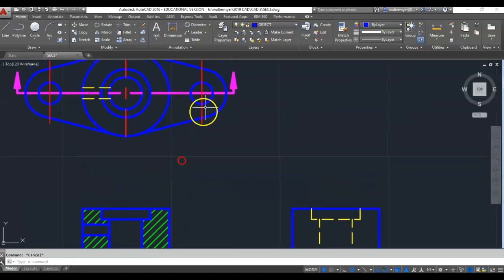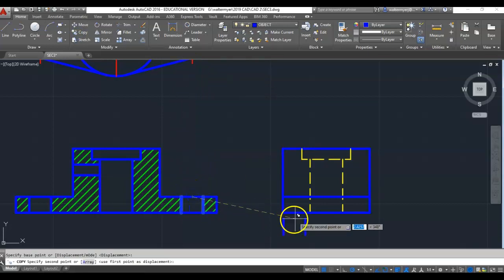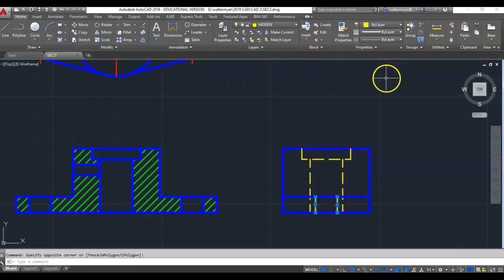This flange, wing, flat part, whatever you want to call it, I will bring over. That will be an object line. I'm going to have the hole that's drilled through it. So again, I'm going to work smart, not hard. I'm going to do copy, grab it by the midpoint. So if I come from the center line down, paste it on the center point of that line, change those to hidden. The other side's the exact same, so it lines up with what's there, so I don't have to add anything for that.